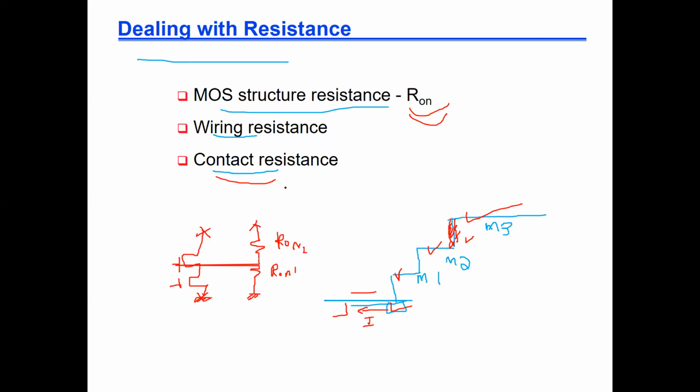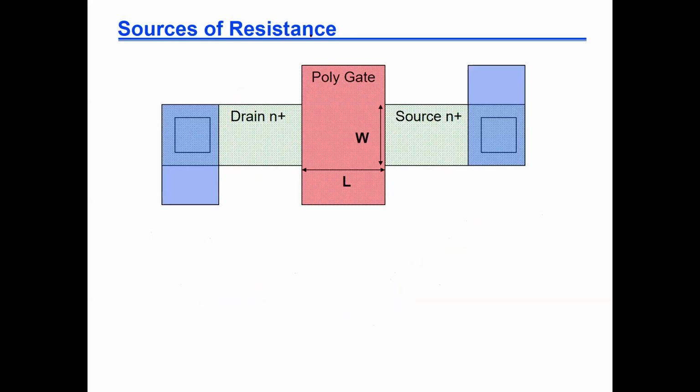Great, so we will start to see how we can tabulate things. We can derive a value for the R on, and we will see how we derive it in the coming lectures. But eventually we will say that those values will scale with my design. Meaning the bigger the W, the bigger the current, and the smaller the R on will be. The resistor will get smaller and it becomes faster, with better delay.